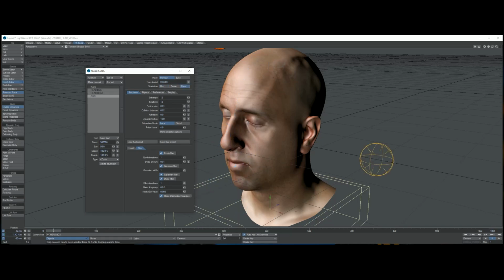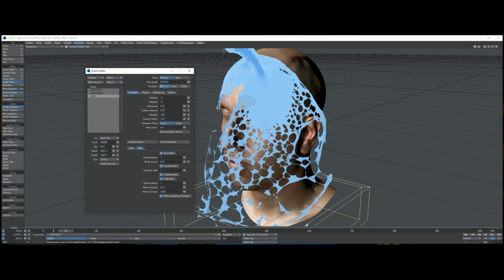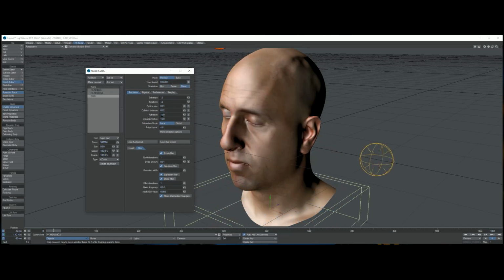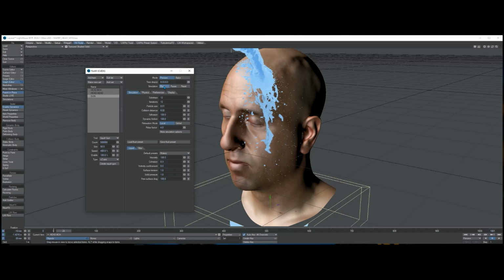So we can study with those simple scenes some kinds of effects you can build with CUDA Flow. And if you make all that very high, for example here the viscosity, make it 200 and this to 0.3, and you take a look, you will see that you can build the wildest things.